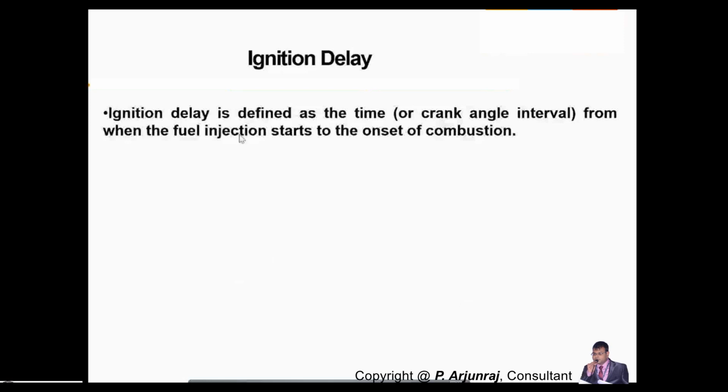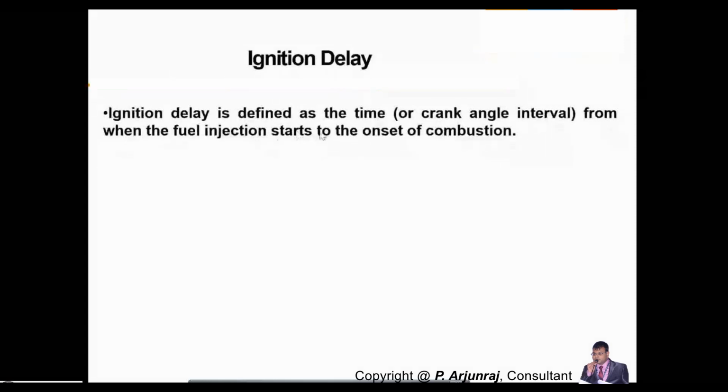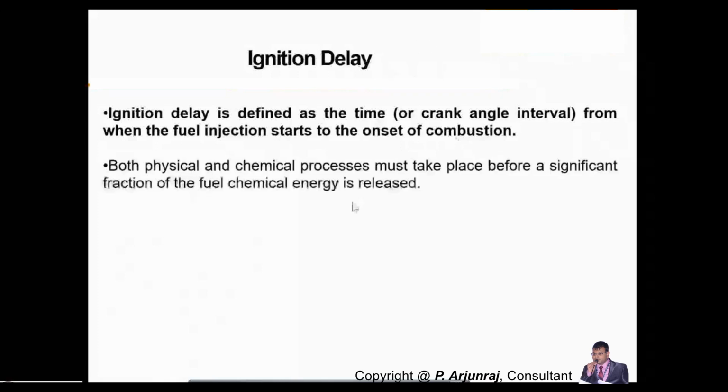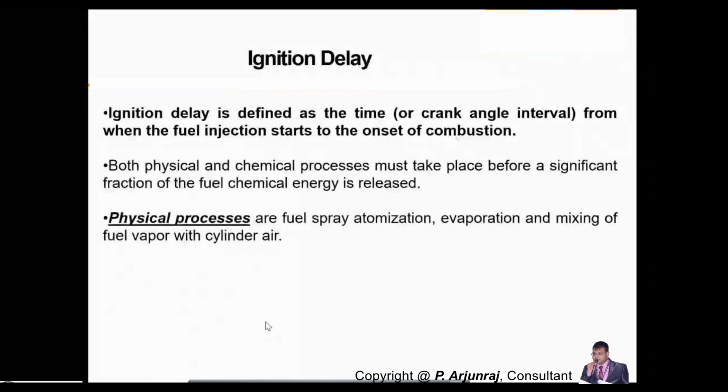When the fuel injection starts, you will not get the combustion immediately. You have some delay for the combustion to take place. That delay period you call the ignition delay period. And this ignition delay, I told you, you have because of two processes or two delays. It can be a physical delay or a chemical delay.